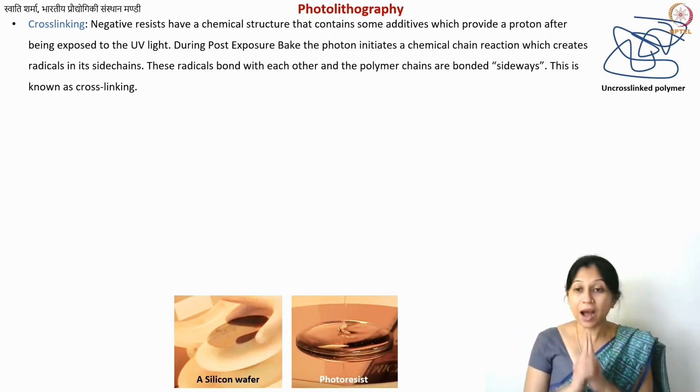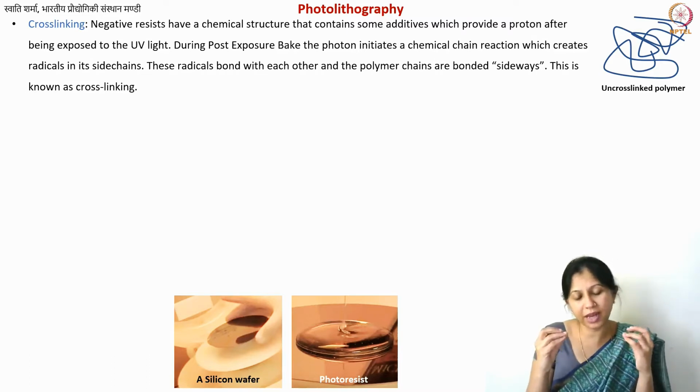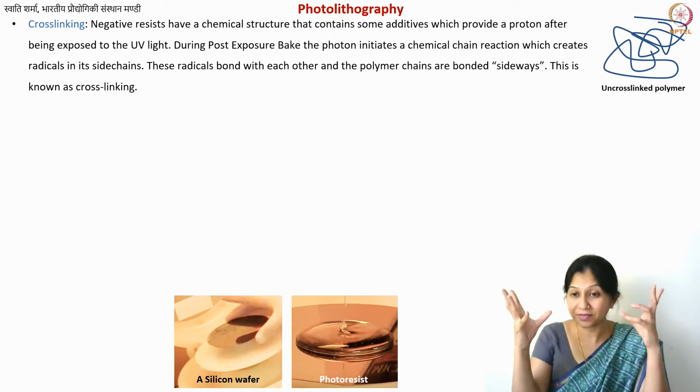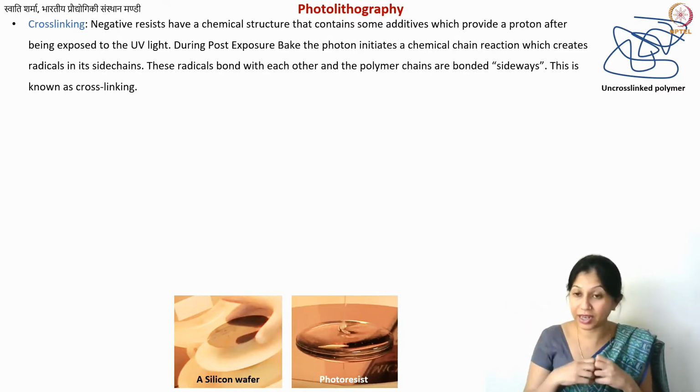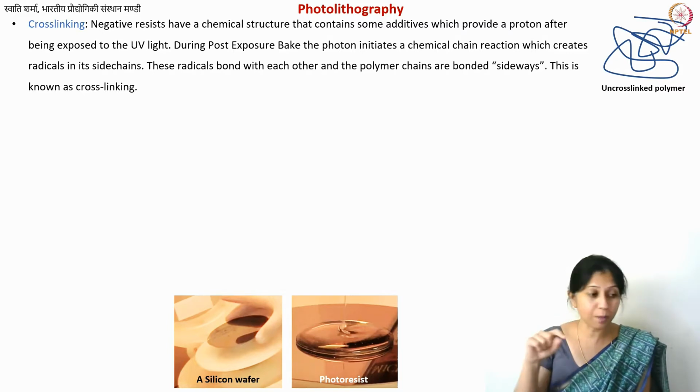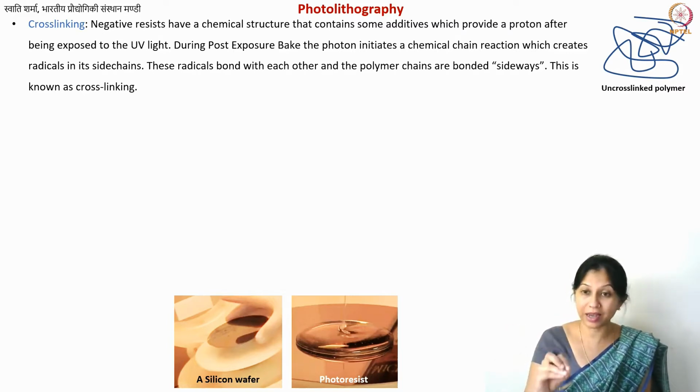Now these epoxy groups, when there is UV light over them, can be opened with relatively less energy, relatively lower activation energy. Now in these commercial photoresists, because they are very highly optimized for the lithographic processes, they also contain something known as photoinitiators.